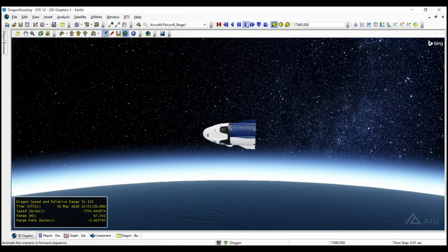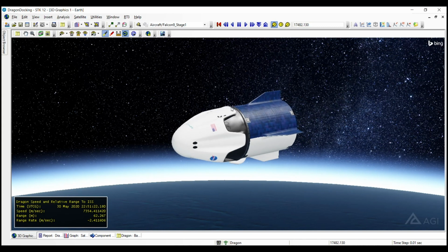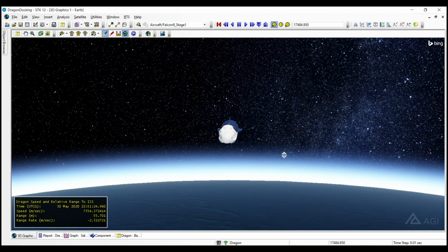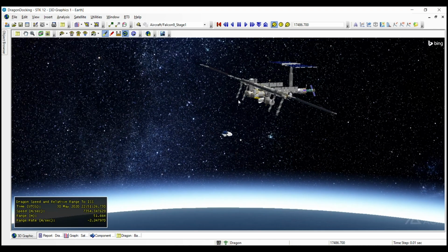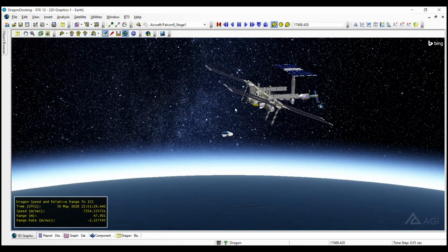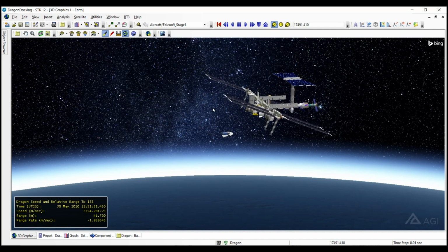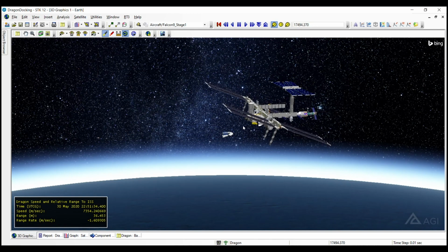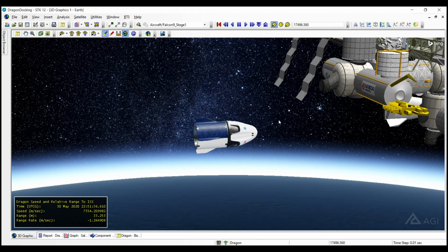Okay, we also need to start adjusting our attitude of the Dragon capsule so that we are in the proper orientation to conduct the docking sequence, right? So we're going to adjust the attitude of the Dragon capsule here, and you can see that this is happening simultaneously as it raises towards the ISS here. And eventually we're going to be offset in the velocity direction or in-track direction by about 10 meters before we execute that final forced motion waypoint sequence to dock with the ISS.